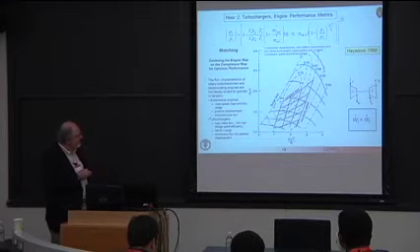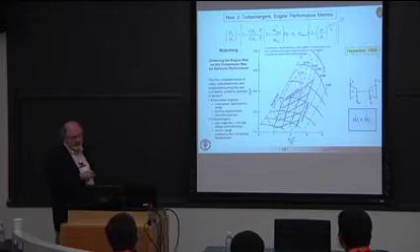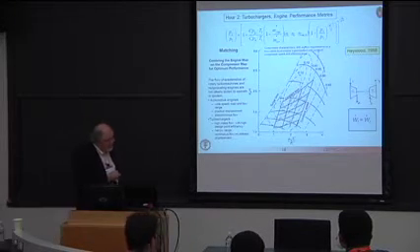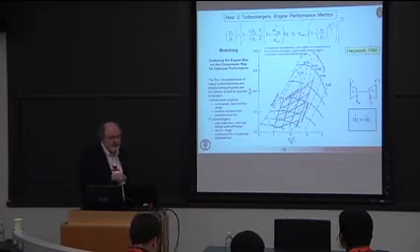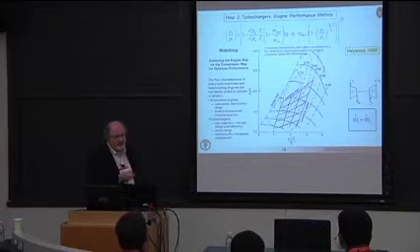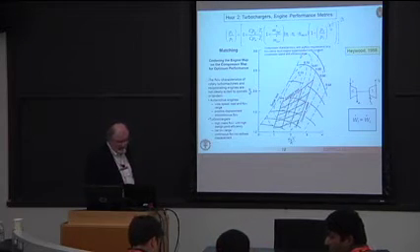So there's quite a bit of skill associated with matching turbochargers, compressors to an engine layout. And of course, one has a lot more flexibility if you have a multi-stage compressor system, or maybe a supercharger and a compressor, because then you're not as limited.